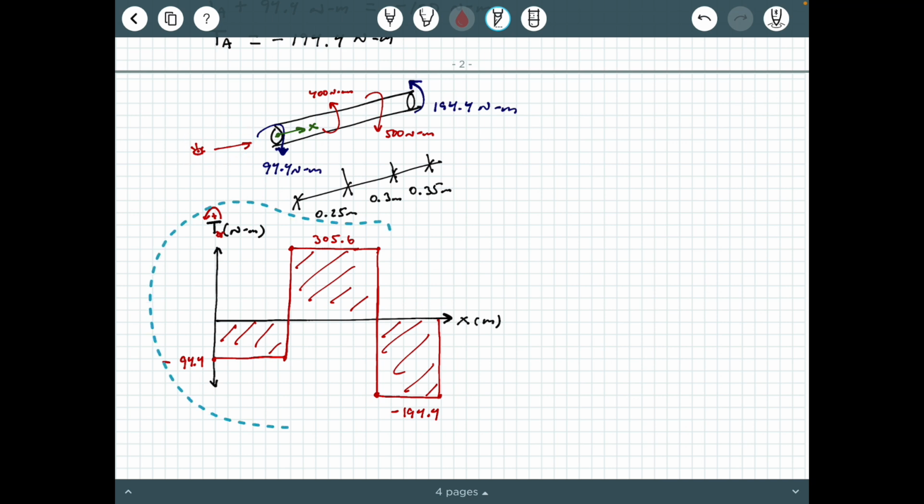And even this torque diagram might be upside down if you define your viewpoints or your directions a little bit differently. So what's important is that you understand really clearly how you're defining your viewpoints and your directions, because that's going to influence the values coming out as positive or negative in a lot of cases. So there are a few different right answers. It's just the values being positive or negative might be different depending on what you call positive rotation or where you're defining your viewpoints. So I just caution people on that.